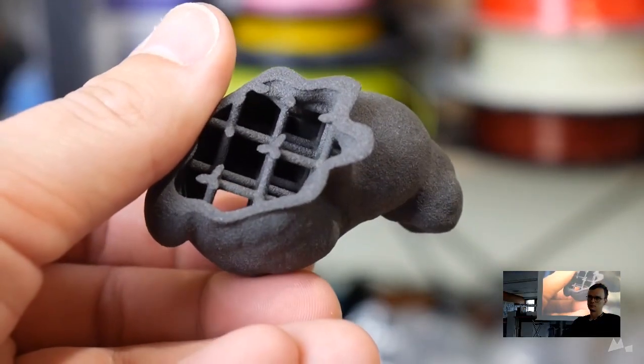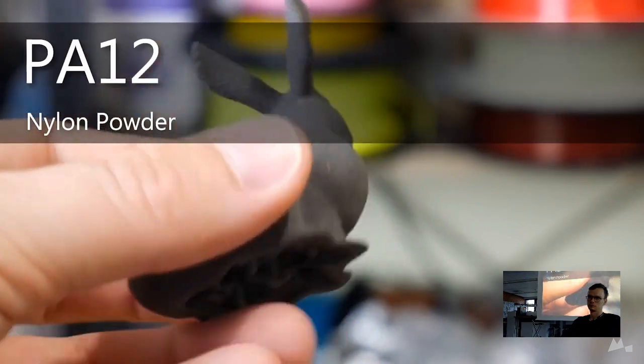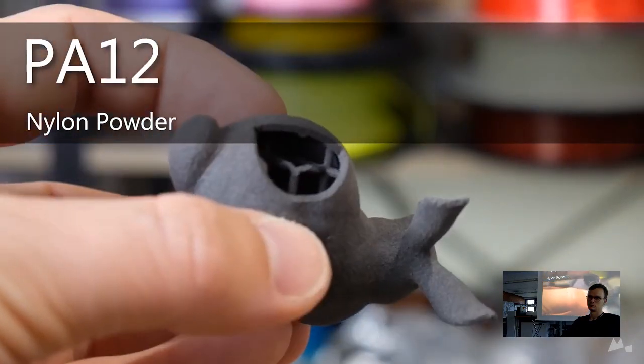And what sort of powder, you might be asking, is it? Well, it's actually a nylon powder. So the Sintering system sinters nylon powder together to form your parts. These parts are quite stable at high temperatures, and they're very strong. I know the Formlabs team were producing bicycle foot pedals and using them. One of their team was actually using them on their bicycles. The parts produced by SLS are very tough. They're not going to be as strong as a melted nylon, nowhere close, but it's a sintered nylon, and it is quite tough, as well as being quite resilient to high temperatures than you'd expect out of a PLA FDM part.